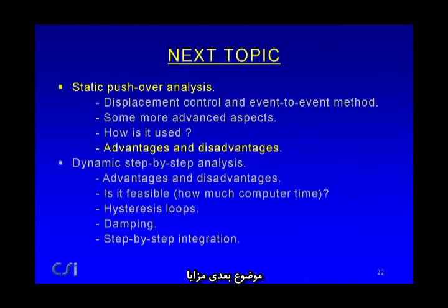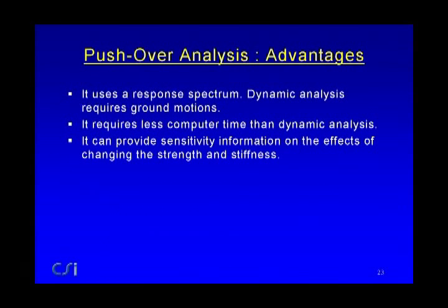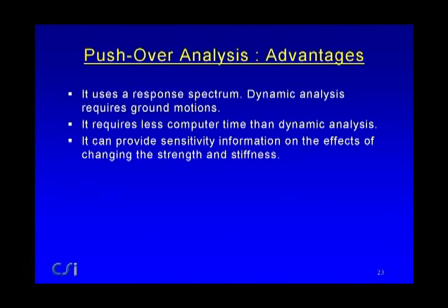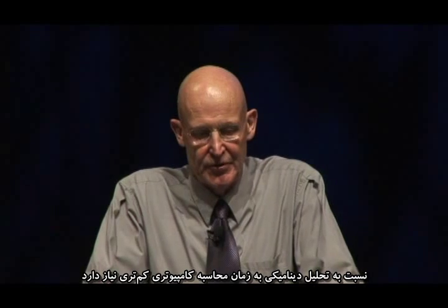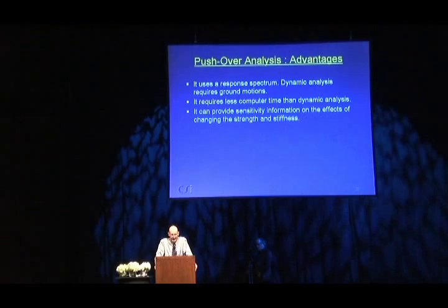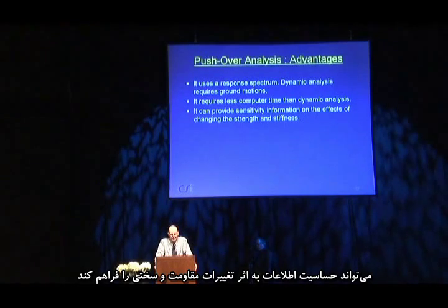So the next topic is: what are the advantages and disadvantages of static pushover analysis? Advantages: it uses a response spectrum, whereas dynamic analysis requires ground motions. That, from a design point of view, is a major advantage. It requires less computer time than dynamic analysis, possibly a lot less computer time. And it can provide some sensitivity information on the effects of changing strength and stiffness.